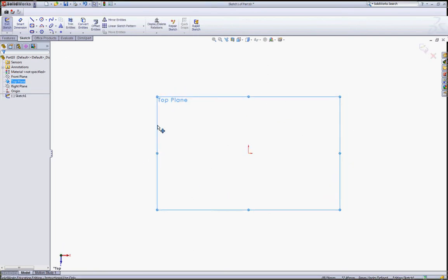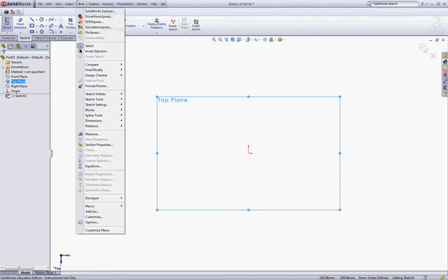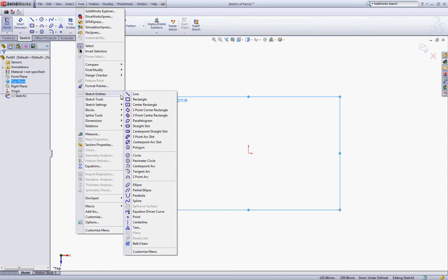When you see Sketch 1 in your work plane, that means you can sketch the circle, rectangle here, because in 2D we have got the sketch entities like polygons, rectangles, and slots, so you can draw the straight slot.